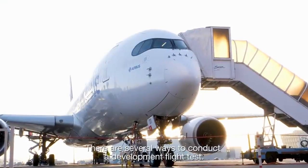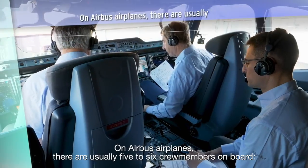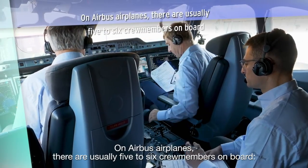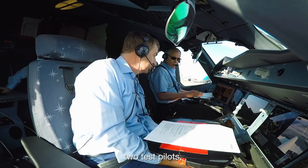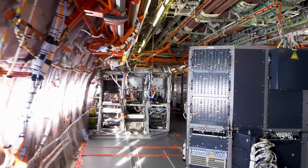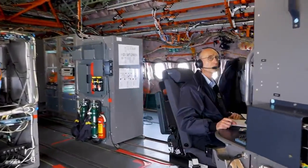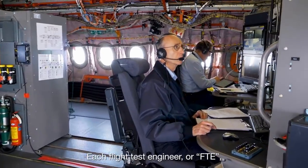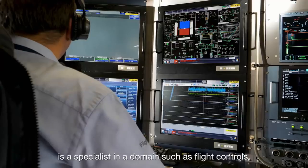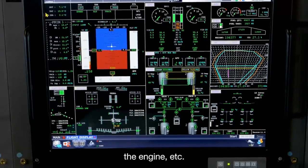There are several ways to conduct a development flight test. On Airbus airplanes, there are usually 5 to 6 crew members on board, 2 test pilots, a test flight engineer, and 2 or 3 flight test engineers. Each flight test engineer, or FTE, is a specialist in a domain such as flight controls, the engine, etc.